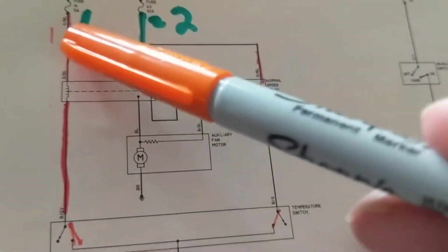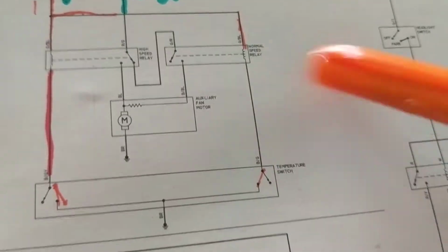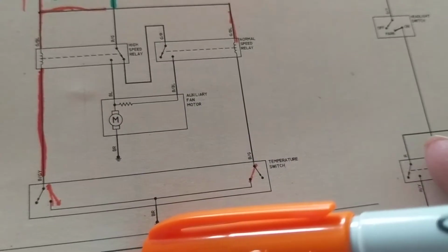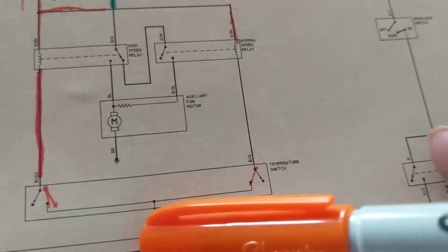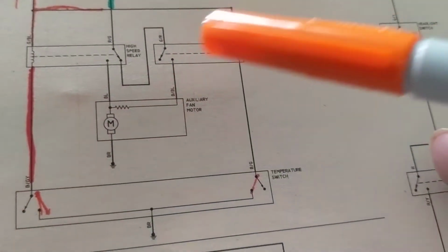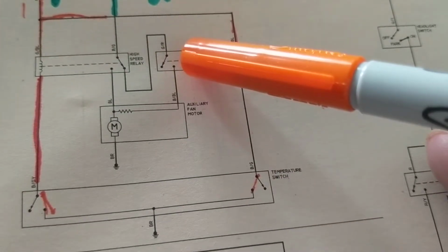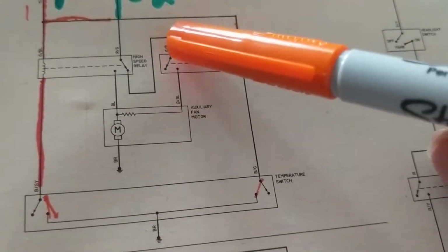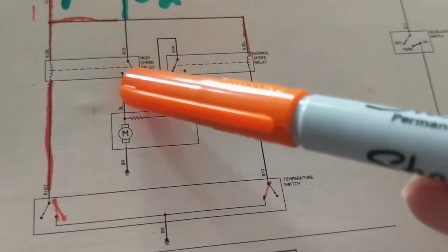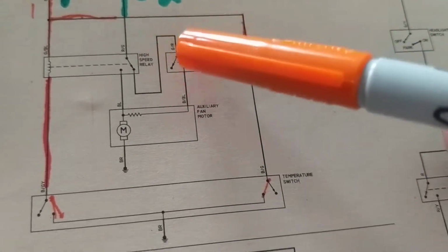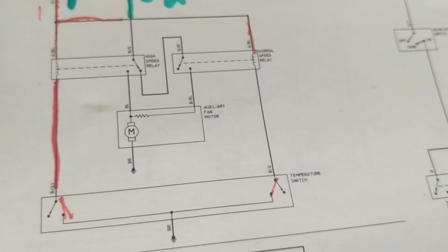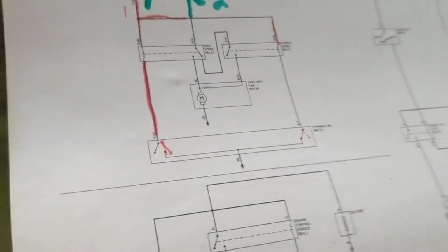What do we say? We need current flowing here, here, here. Now, in order for this to be activated, I need this switch, the temperature switch, to be in this position. When that happens, current flows through here through a complete path. What happens next? This is being pulled in. Now it's in this position. Therefore, the current flows through this one that is not activated, through here, through this one that is being activated, through a resistor dropping the speed. Beautiful circuit. It's a beautiful circuit.